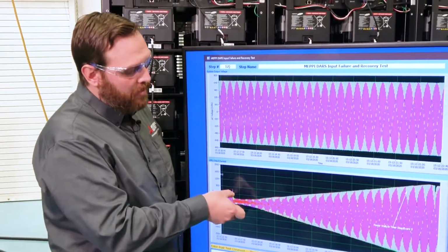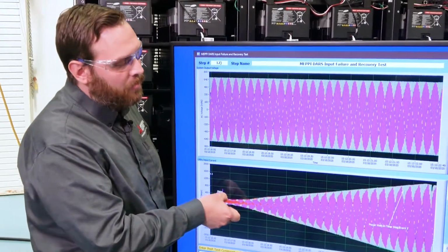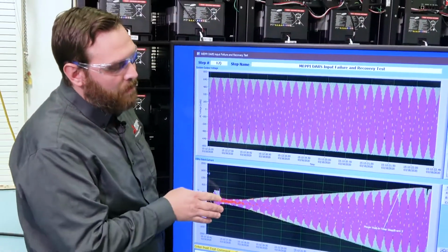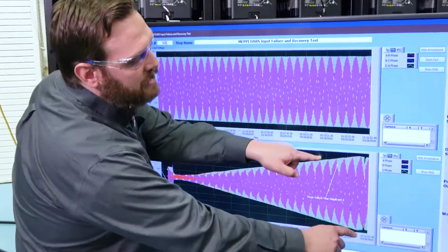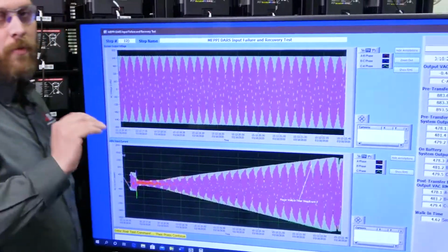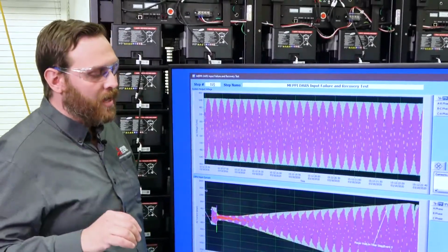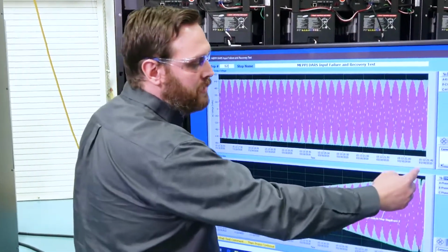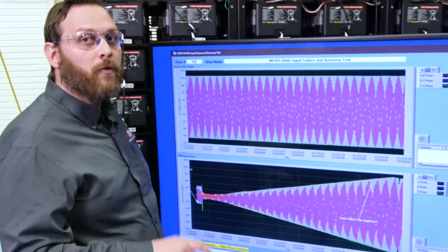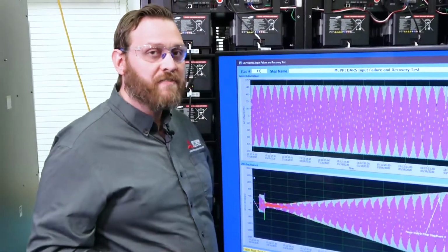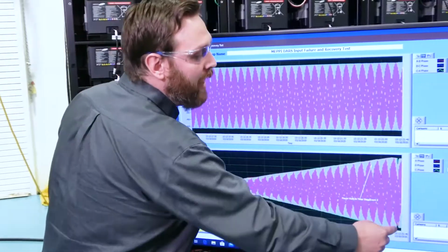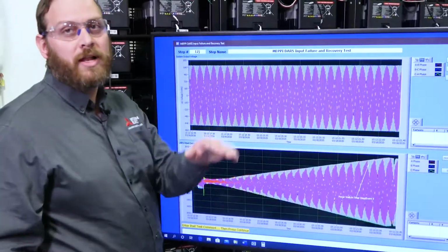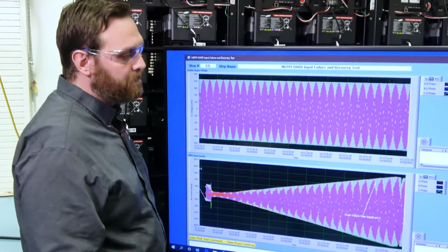The converter then minimizes that current to those filter caps and then begins walking in the UPS in a nice slow and steady ramp up to full load of the UPS at that point in time. The time period on this is currently set at 10 seconds for full load. Since we were at 50% load on the UPS, this actually will run for exactly 5 seconds until it's fully loaded at that low point of the UPS.